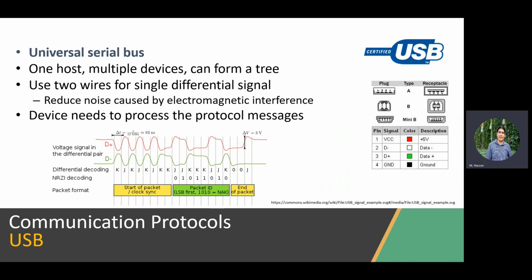Okay, good. So a differential signal is a very common approach in electronics in high speeds, because instead of using a single wire for the same bit of data, I'm using two. And it's very common in clocks, especially because clock is very sensitive. If you have a distorted clock, your system is done, right? So you'll find in many systems, clocks are differential. Differential means instead of saying I am currently sending one bit as one, which means interpret this bit as one, I'm going to send two wires. One has the actual value, the other one has the negated value. So it's 1 and 0, for example.